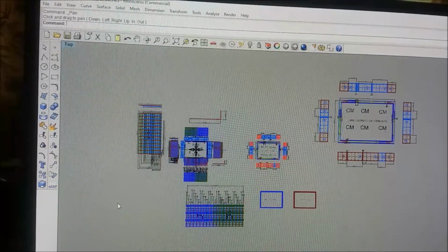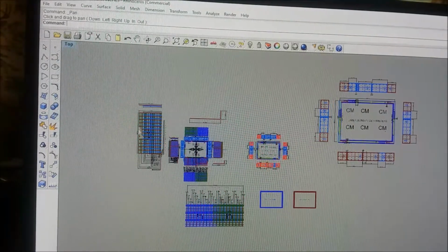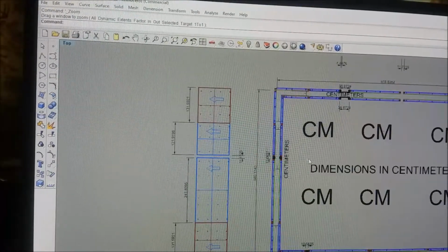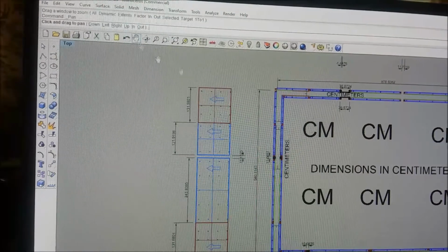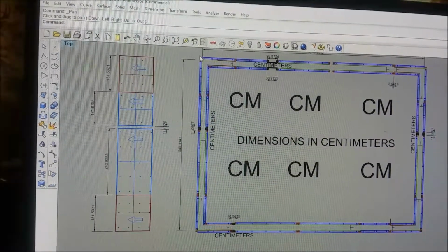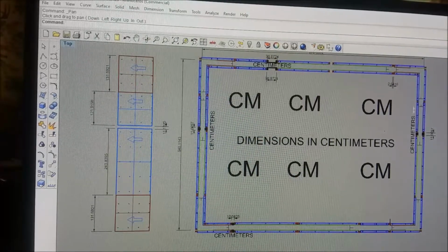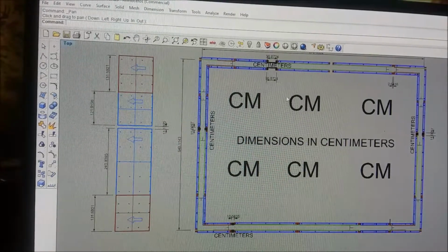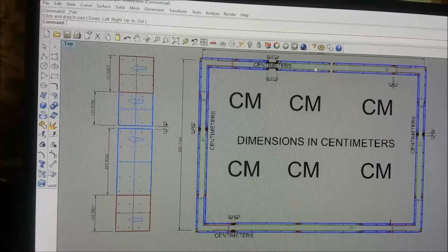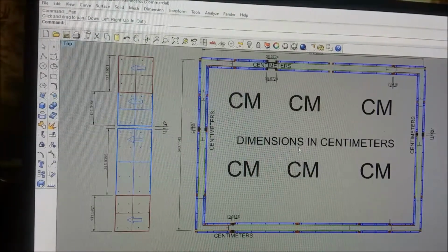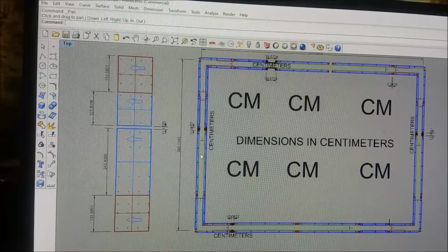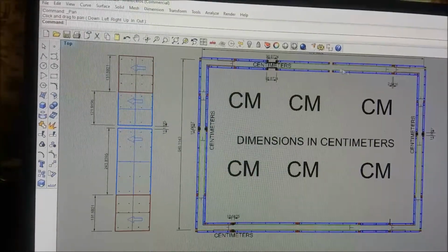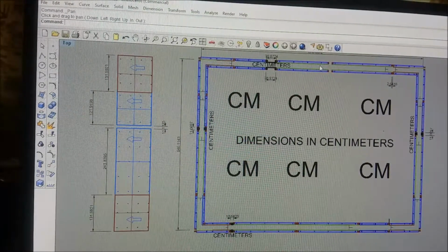And if you're doing that, you want to figure your weight or your load. You can quit watching now, we're just talking. If I take the floor that's under this septic tank, from corner to corner, and I draw another line, corner to corner, it's going to make 4 triangles. If I take the weight of this concrete triangle, that can be the load that's on a beam on that side. And this triangle is a different shape, so it's a different area. It'll have a different load per square foot. So you can divide up a rectangular room into 4 triangles to figure out how much weight to assign to each one.